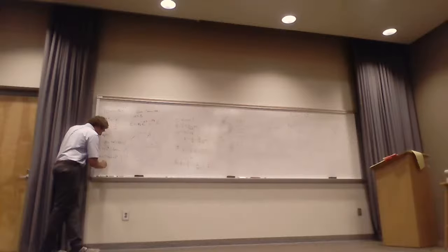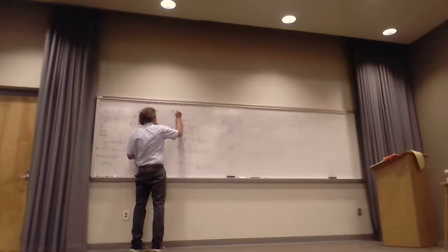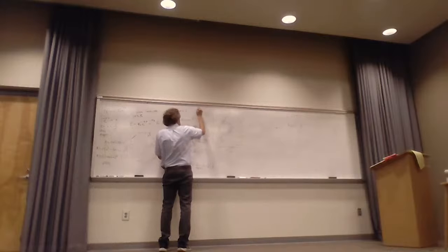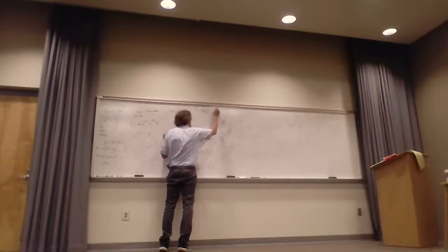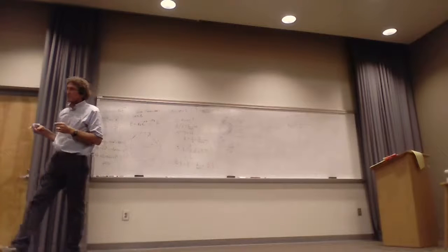And usually the skin depth is much less than the radius, so we say that that area right there is about equal to simply 2 pi A times the skin depth. And the skin depth, remember this one, is equal to 1 over the square root of pi f mu sigma. It's really 1 over alpha, right? And alpha is the square root of pi f mu sigma.